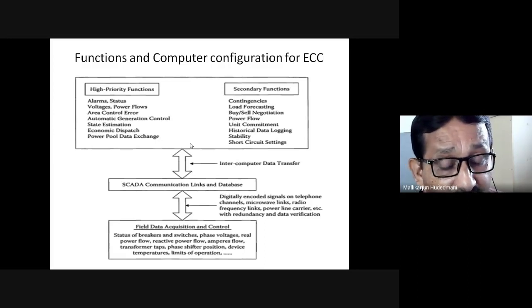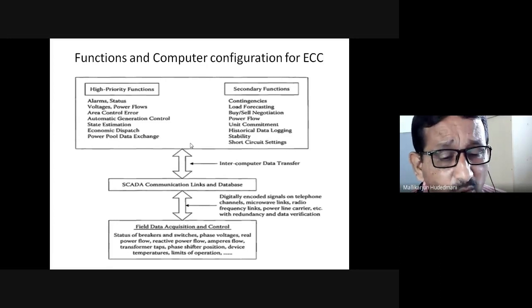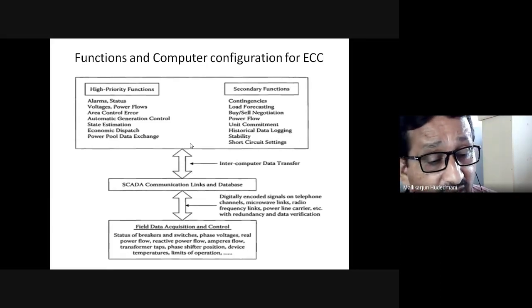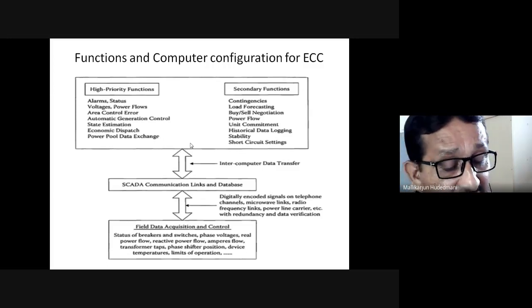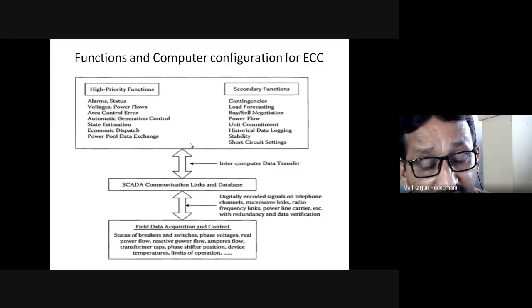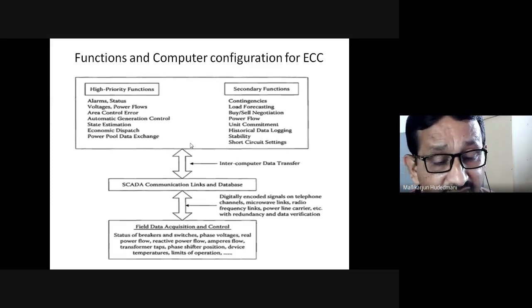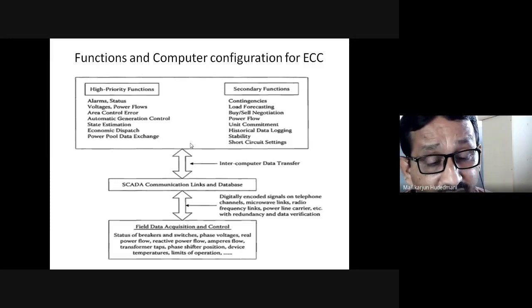Then the continuous study of power flow, which is the backbone of power system operation, should be done on the secondary computer continuously. It provides the P, Q, V, delta data periodically to make my control action on the other side. And unit commitment is an important aspect that we were defining continuously. I should see to it that the committed units are really delivering me the power or not. If they are not, which is the next best unit I must combine? And which one is to be eliminated from the schedule? This kind of commitment schedule has to be systematically viewed in the background.